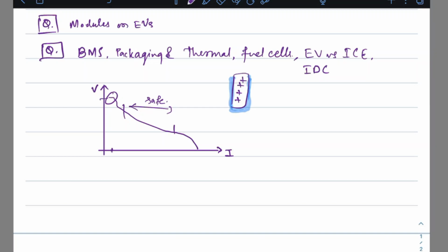Each branch is treated as an independent entity by your BMS for charging purposes, but to your motor it is perceived as one single source of energy which is giving it the current it needs to accelerate you or keep you cruising. So it is not only a dual system, we can make it triple, or, sky is the limit. I mean, battery pack size is the limit. You can make it multiple.